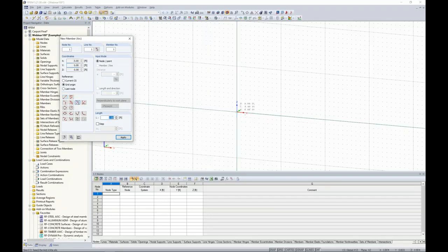So I snap to the origin at 0, 0, 0, and then my second point can either be defined on my work plane here, but in my particular case, I don't have exactly 1 foot increments for my second point, which is what the default is for my drawing grid. So what I can do is just type in the coordinate points directly at 4.42, 0, and 11.